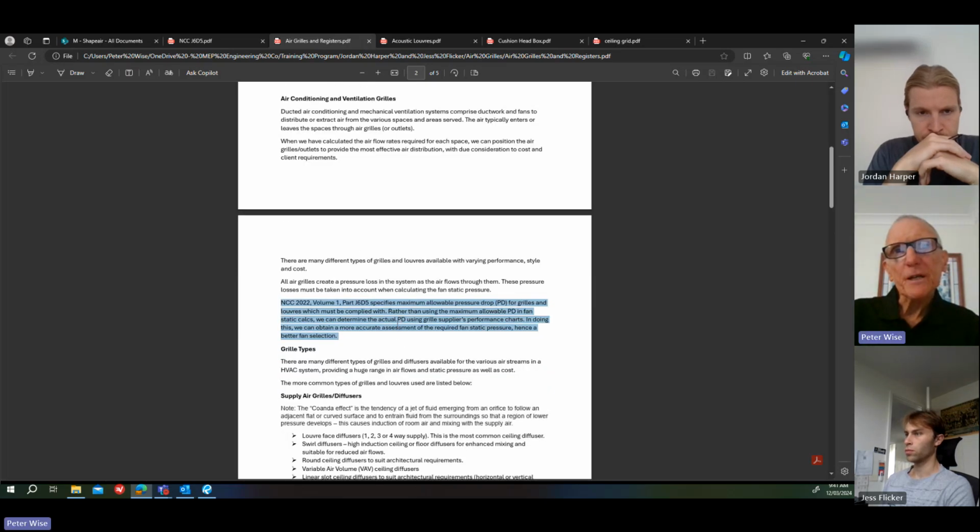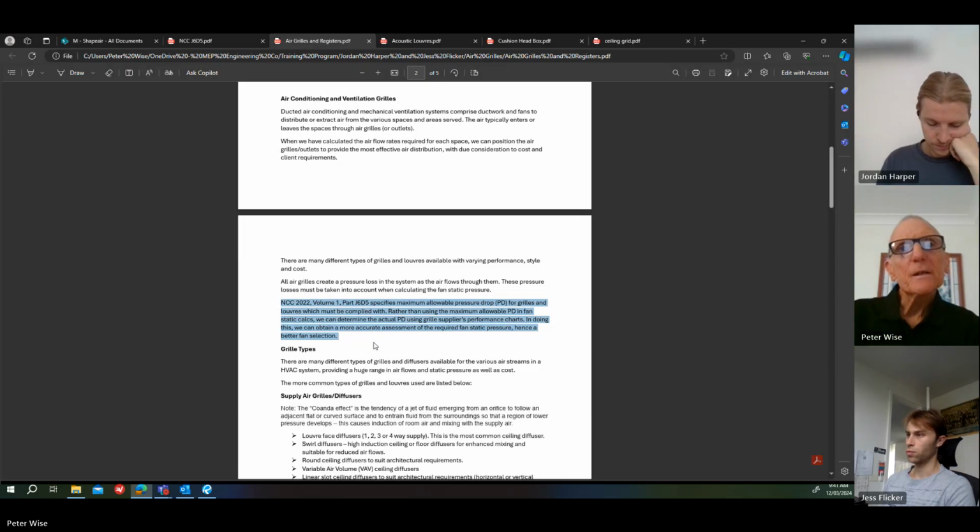So that's what I'm saying there. Rather than using the maximum allowable pressure drop in the fan static calcs, we can determine the actual pressure drop using grill suppliers' performance charts, and we can get a more accurate assessment.